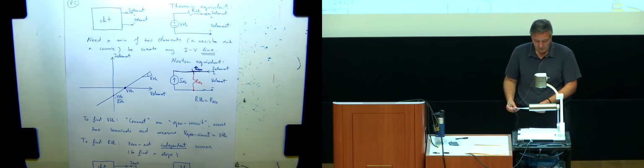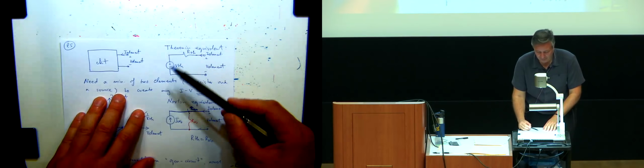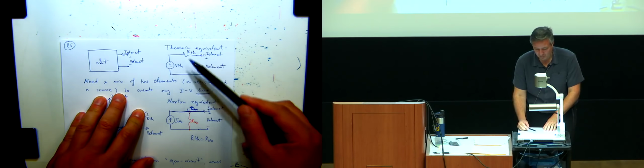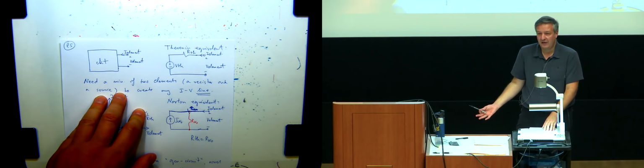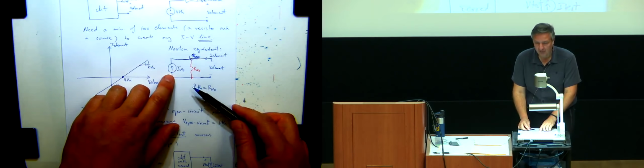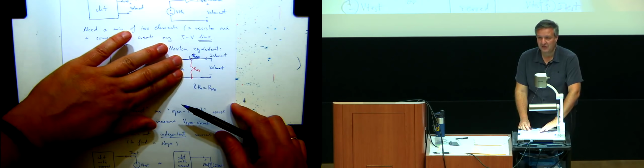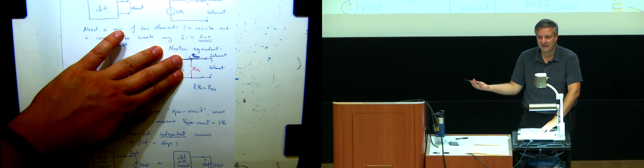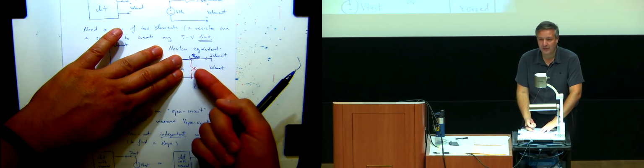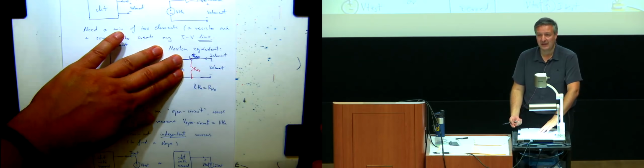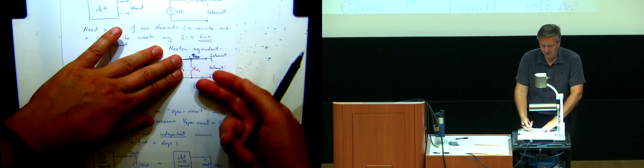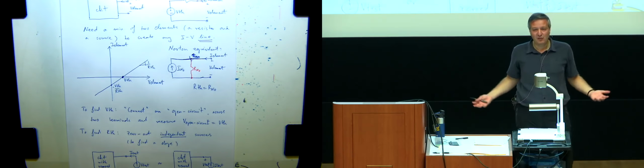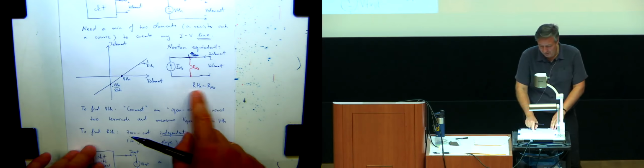Right? I mean, simply looking at it, when I null this source, it shorts, right? It creates a wire here. So, this thing becomes just R Thevenin, right? When I null this source, it just becomes an open, right? So there's no current going there anymore, it doesn't exist anymore. So the only thing that remains is R Norton, and these two are supposed to be the same. So I have R Thevenin here and R Norton here. The only way for them to be equivalent circuits is these two values are exactly the same, right? So R Thevenin equals R Norton.